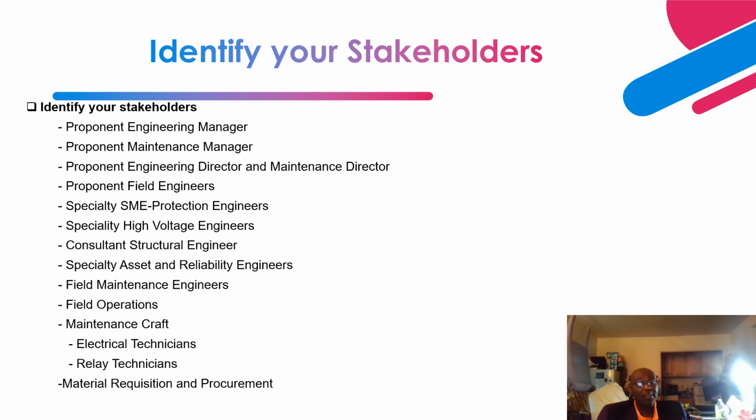You need to assess that foundation. If you have a transformer that has been in operation for about 40 years, sitting on this foundation, short circuit stress and cyclical loading of the transformer weaken the foundation. So the foundation itself has to be assessed by a qualified structural engineer.